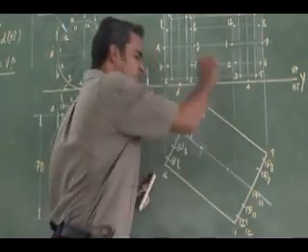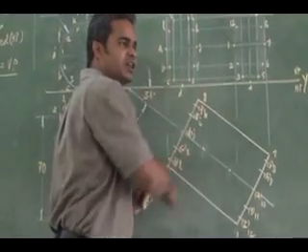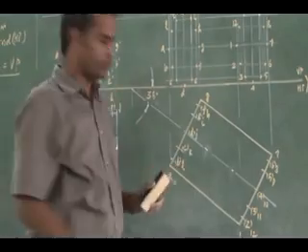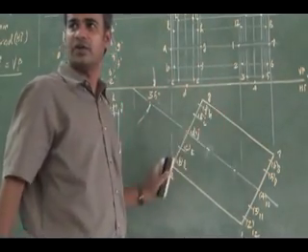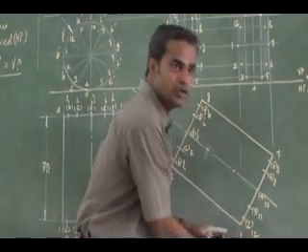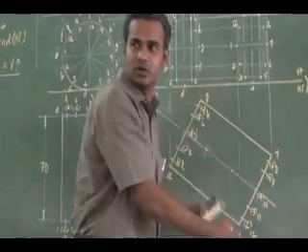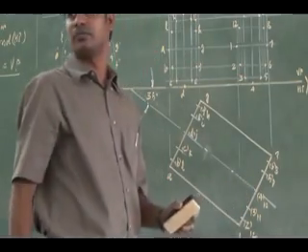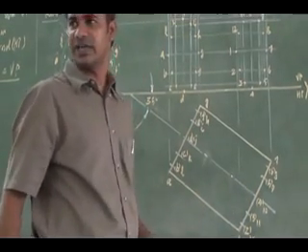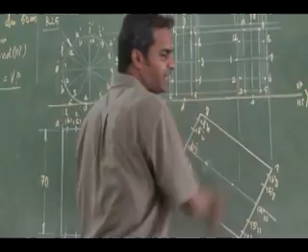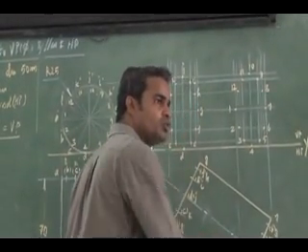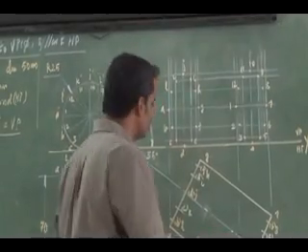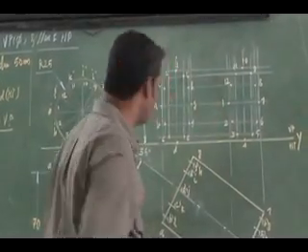You don't put the notation on top, because you have to project the corners to get the final front view. Show the notations inside the cylinder for the top base and below the cylinder for the bottom base, so that while projecting they don't interfere with the projectors. Then I can project to get the final front view. From the final top view, all the corner points of the two bases will be projected to the final front view.